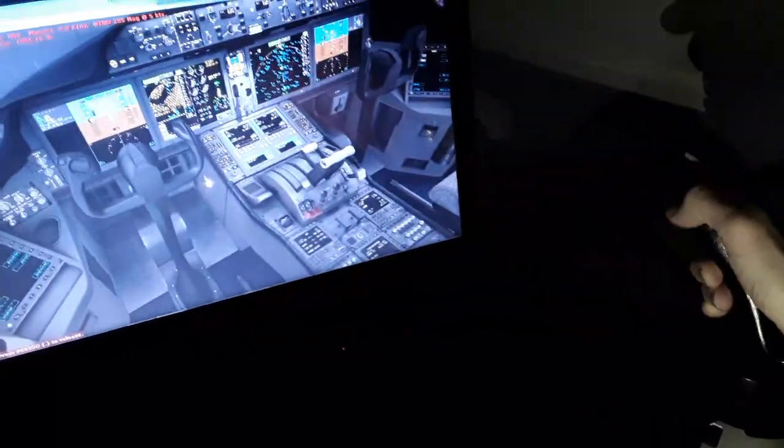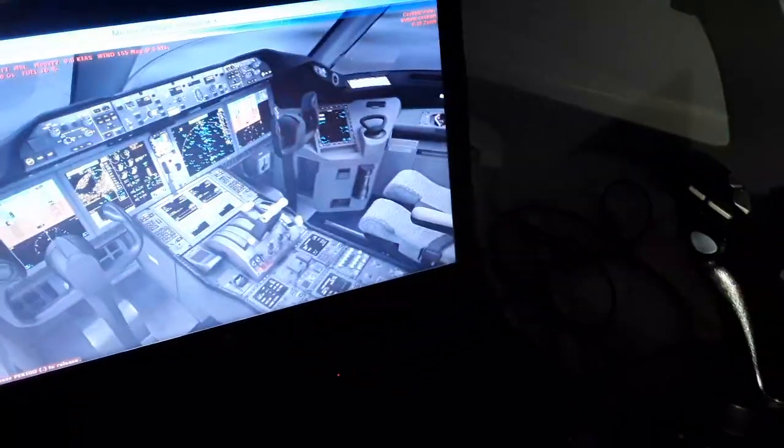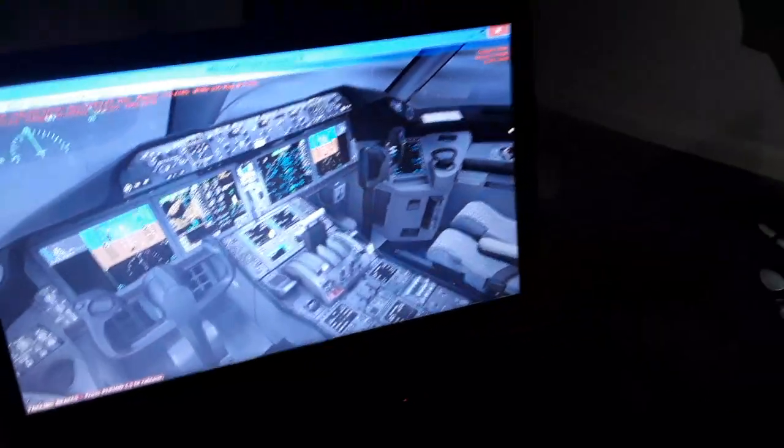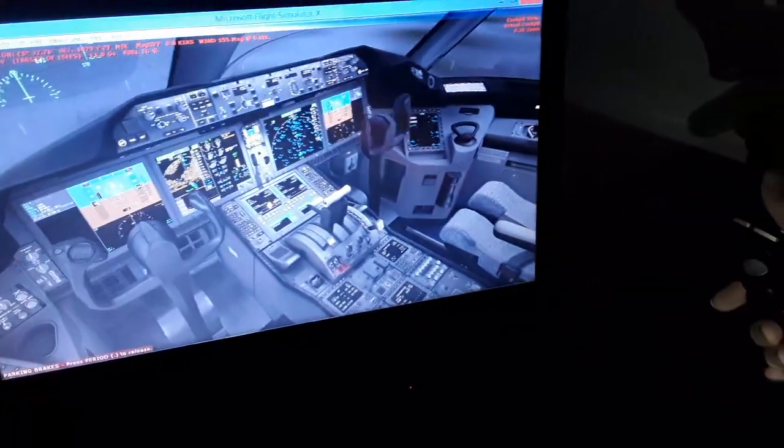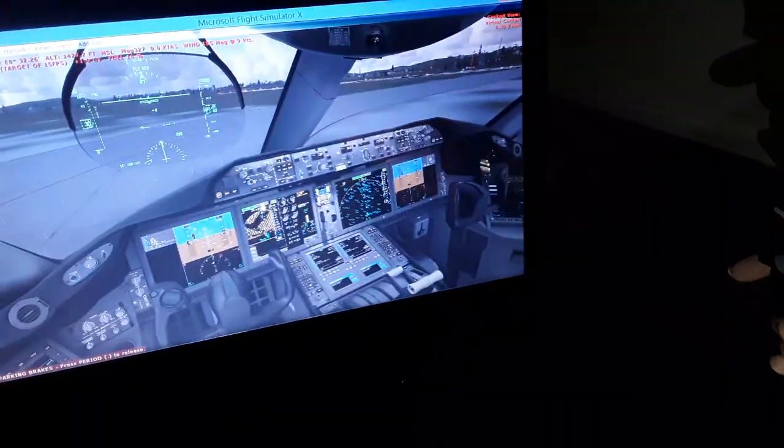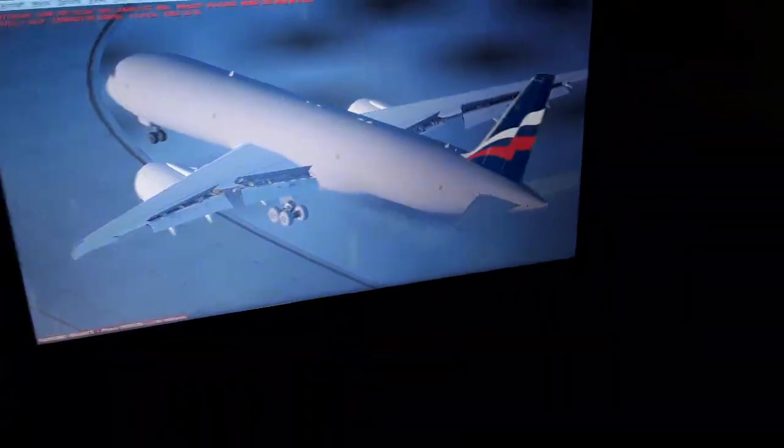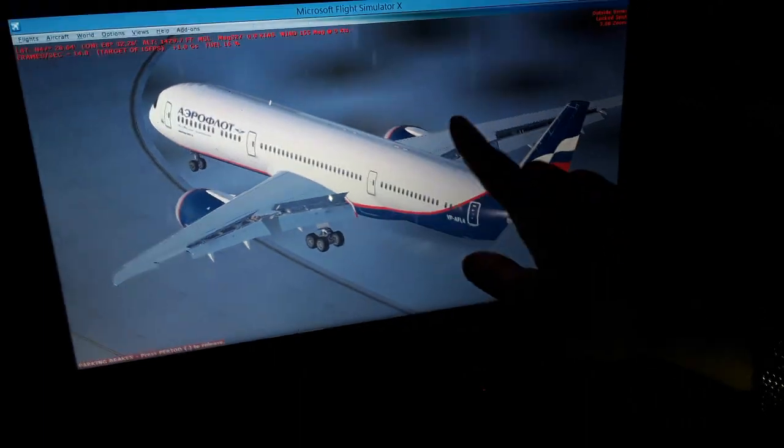When flying, we need to apply the side stick down in the Airbus aircraft, and also the yoke in the Boeing, and also the thrust levers forward to increase the thrust and decrease the angle of attack of the aircraft as we fly, using the side stick down. So this is the stall avoidance maneuver. We need the mean aerodynamic chord.